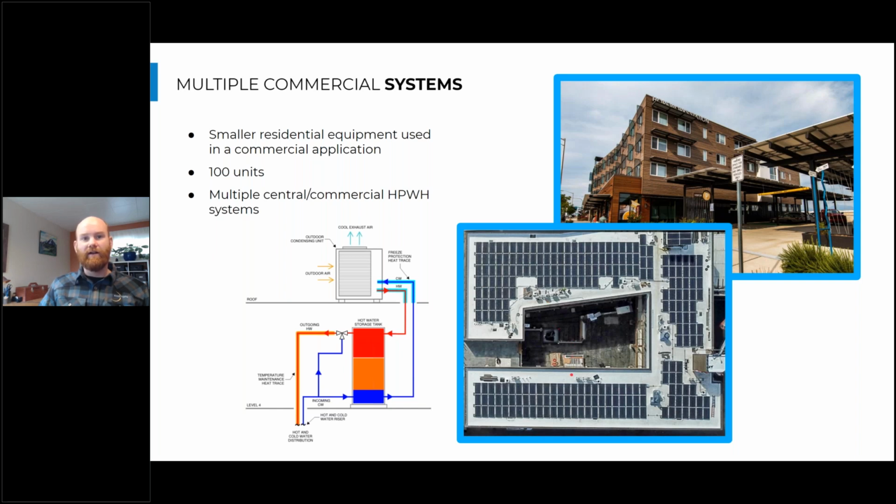And we can locate a few of those heat pumps, and those are really just serving those units vertically. Once again, this is using the Sanden CO2 heat pump water heater, which uses CO2 as the refrigerant, which can work down to very cool temperatures. So we can locate it on a rooftop. And we talk about refrigerant selections in some of our other courses, so I encourage you all to attend those, especially if you're working in the engineering world.